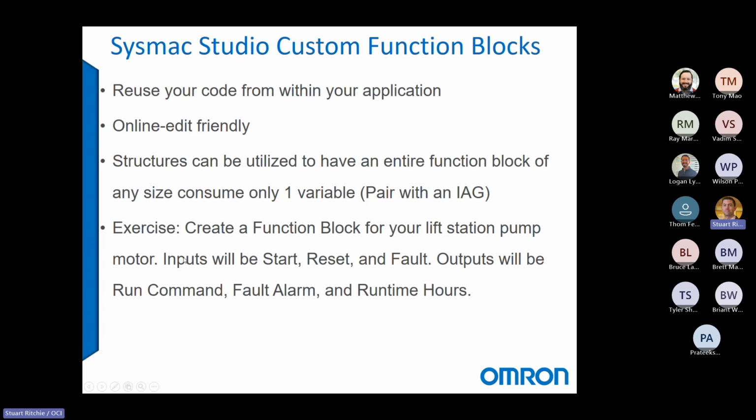So our inputs are going to be start, reset, and fault. And the outputs will be the run command to start the motor, the fault alarm, and also how many hours that motor's been running for.